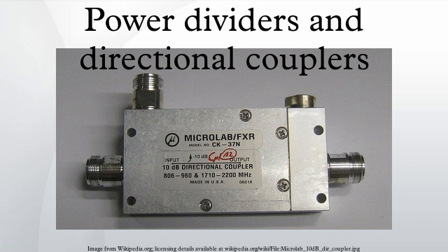It is possible to produce a coupler with a coupling factor different from 3 dB by making each λ/4 section of the ring alternately low and high impedance, but for a 3 dB coupler the entire ring is made of √2 times the port impedance. For a 50 Ω design, the ring would be approximately 70 Ω. The S-matrix for this hybrid is given by the following.